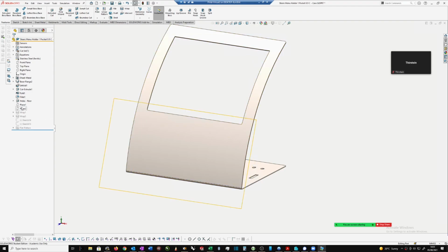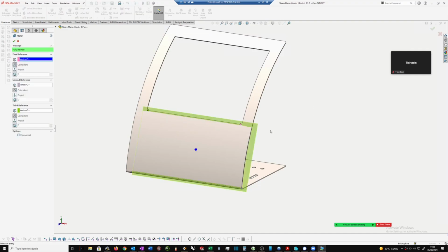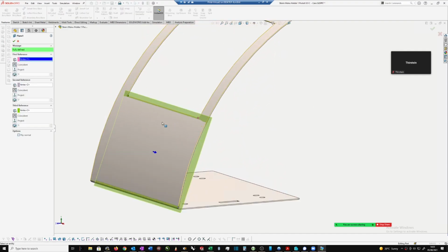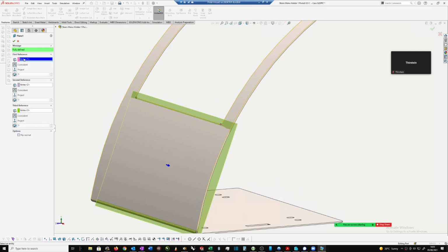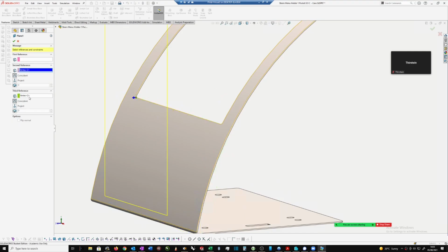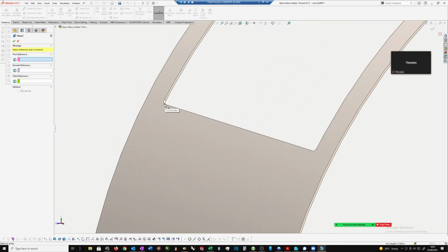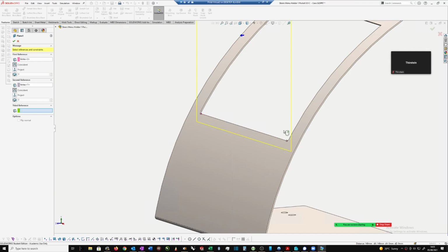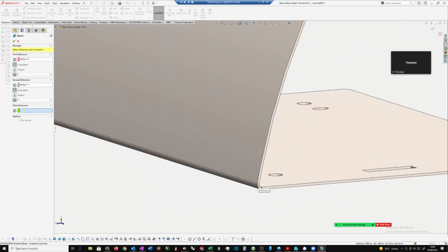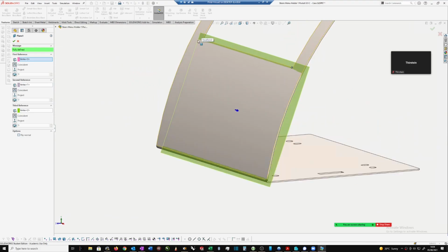So once you've got your DXF and you know where it is, you create your planes. Like I've created this first plane. Let me show you what I've done here. I wanted a plane which was tangent to this curve, but only over a short section of the item. So let's delete them and start again. I selected three vertices. That's not right, that's an edge. So I selected a vertex, that one there, and another one, and then a third one. Now you can see the plane goes through this top curve at 3 points, so that gives it a nice kind of landing, and it's fully defined.